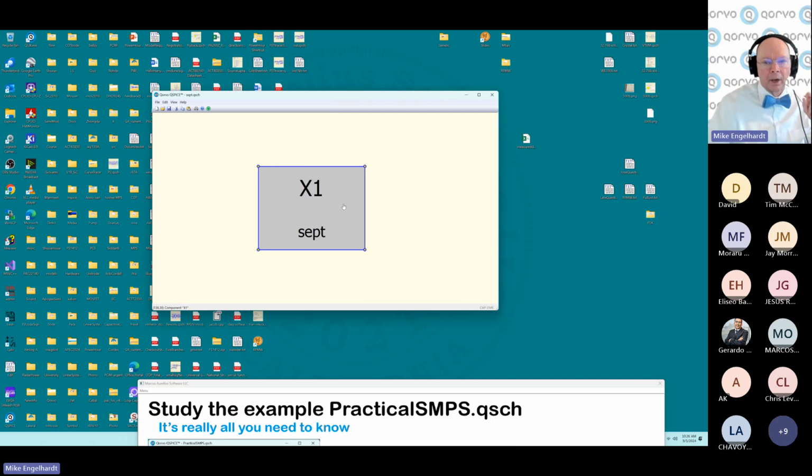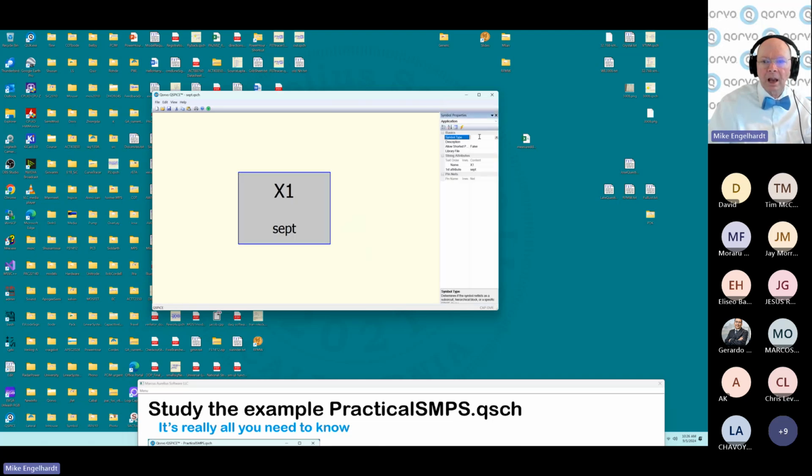So to do that, we have to change this hierarchical entry to be a DLL. To do that, we right-click, show symbol properties. The icon is this little eye of the Illuminati. We come into symbol type. Do we want it to be a diode, a transconductance, an inductor, all these things. But at the bottom is a circle with a slash through it, a little Norsk O. I use that because it looks like a 0 on a computer terminal. And this now is a DLL. And now I have different right-click menus for this.